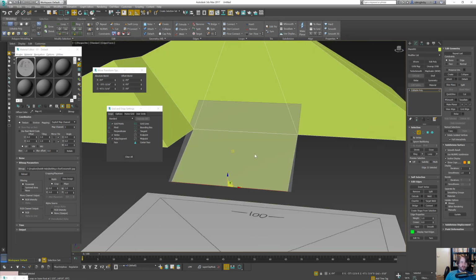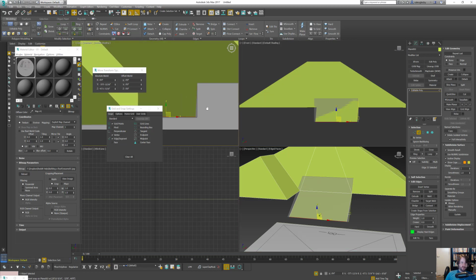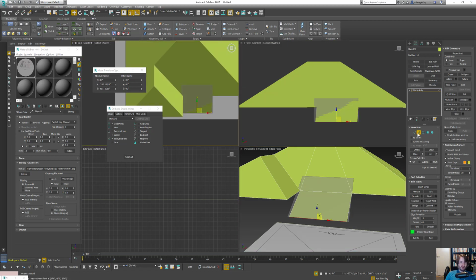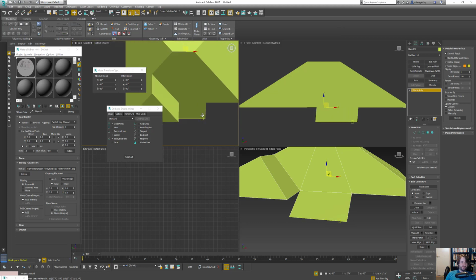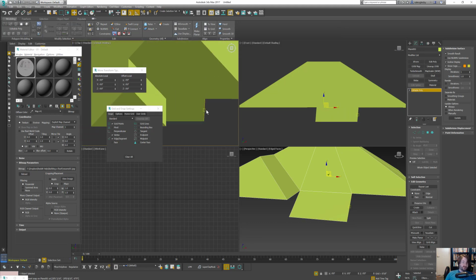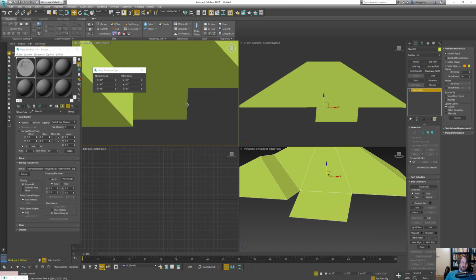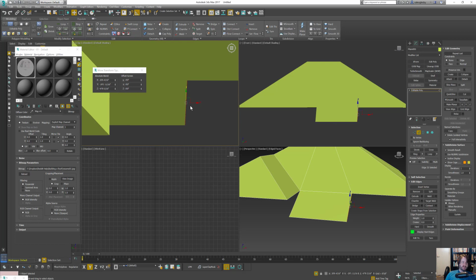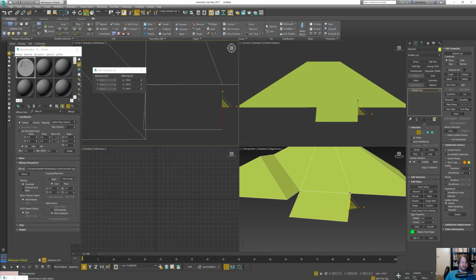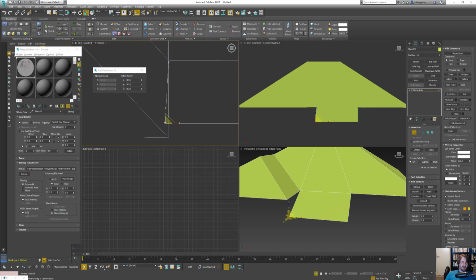Okay, and then there's things that you'll want to watch out for, which is, I don't need that image anymore, I just have the roof. We're looking straight down, so we no longer have a straight edge here. So we're going to fix that just by clicking this edge, getting the scale tool again, X, right click to go to 0. I'm going to do the same thing on this. But on this one, instead of doing that, I'm going to move it to match it here.